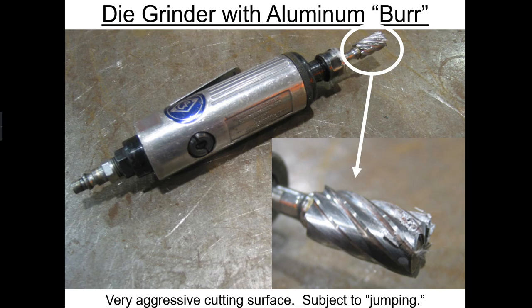Now, something to understand later on is removing material. Part of your quality control program is going to be removing material with a burr. This is a typical burr we use to remove material. It's made of tungsten carbide and has very special flutes on it that take aluminum and rip it off the surface without adding anything to the cleaning zone.